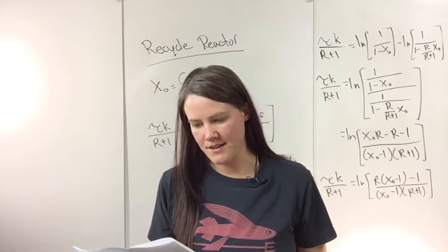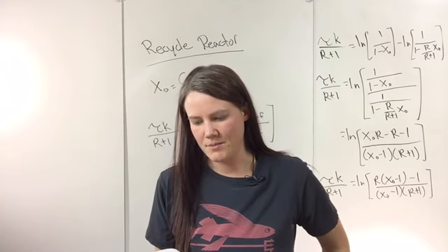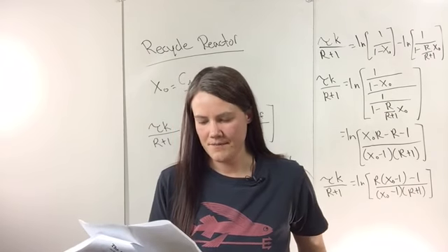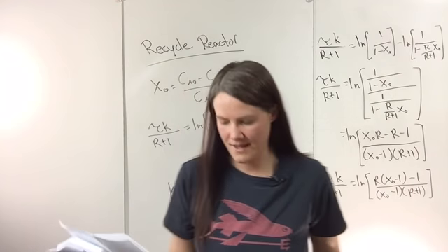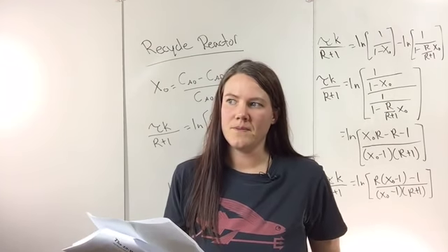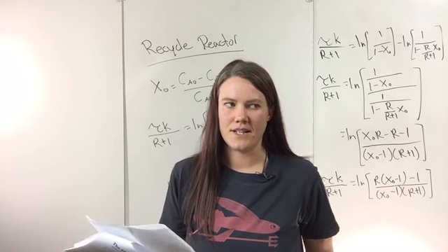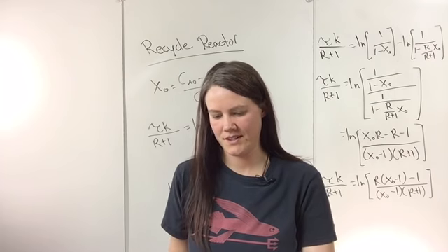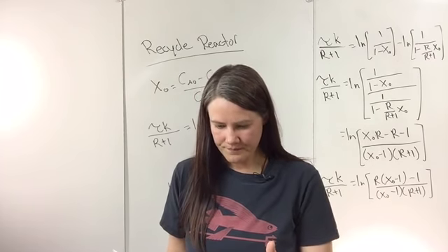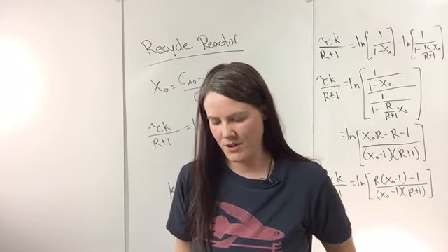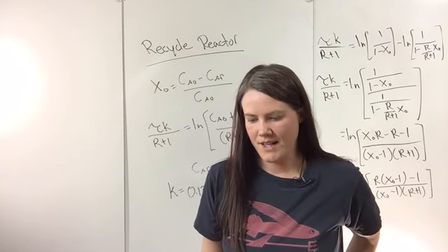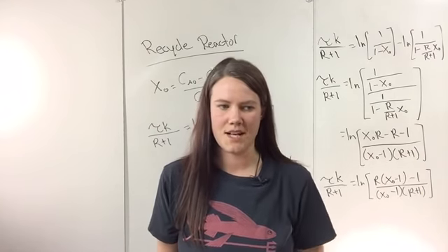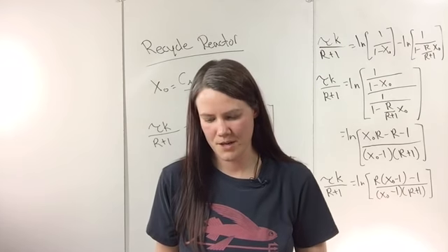To get an analytic solution, you basically need to assume there's no volume change, so epsilon is equal to 0. If you don't, you'll end up with 2 ODEs, and you need to use a solver. You can't really get an analytic solution. I'm not planning on going over a problem on that because nobody really asked, and it's the same thing as the other stuff. You're just taking one more step, adding in the pressure drop.